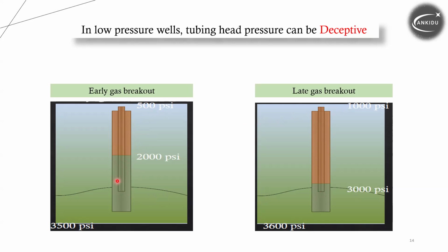If we just take this simple idea of the wellhead pressure, not taking into account any damage, corrosion, tubing issue, annulus issue, scale, etc., for wellbore problems, then it's not enough for low pressure wells. Tubing head pressure can be deceptive. So don't rely on these pressures. You have to check beforehand what the well was doing. Do you have any relevant data from your simulators? What does it tell you regarding the performance before the well was shut in?